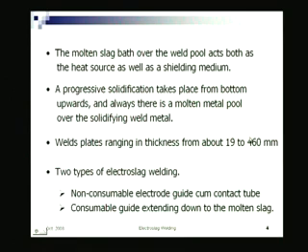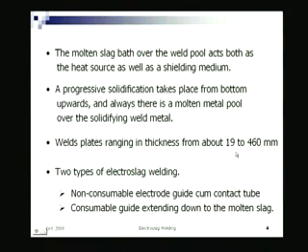So, God knows if a 1 meter thick plate has to be welded, I do not know whether that is feasible, but apparently theoretically possible. A 460 millimeter plate is definitely not in shipbuilding, something else, probably nuclear reactors and all that, right. The shielding things they do possibly there, but as far as ships are concerned, one may encounter plate thicknesses of 80 millimeter, 100 millimeter like that, right. Generally not beyond that as of now. But you can see even a thickness of 460 millimeter, that means half a meter thick. This is the thickness, not the breadth. Half a meter thick plate you are welding in one run, right. That is a terrible thing.